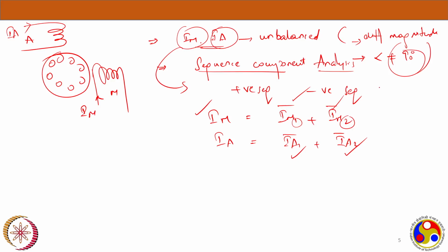Now how can we apply this concept to our single phase induction machine? Let's say we have a single phase induction machine that runs on a single winding. We saw that there won't be any starting torque for the motor, so it won't start unless you give it an external force. Therefore we have to do something about it, and then we started discussing this concept of auxiliary winding.